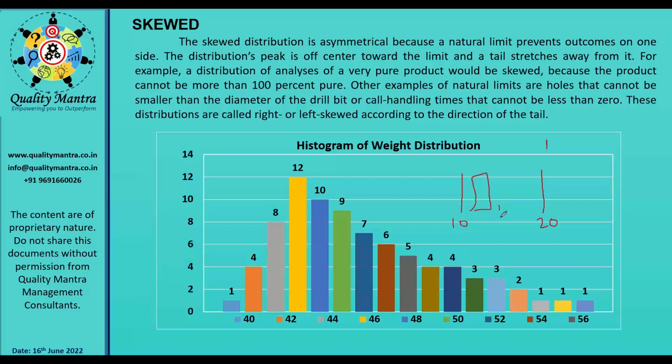He wants to make it between 10 to 15 only. Why would he give you more? Because you are not paying him for this much. You are paying whatever the specification, whatever material he supplies between 10 to 20 micron, you are accepting that. So as a supplier, he can choose to produce most of the product between this one, and very few will be at this range.